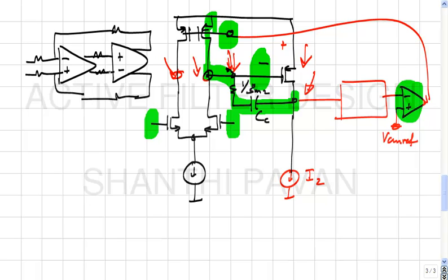So what he is saying is that okay, what about the input here, right. If I yank this now, will this guy get out of trouble, right. Please note that if this is 0, unless this is 1.8 volts, this will not go to 0.9, you understand. So unless you really wiggle, it will not get out, okay. So this is a very practical problem, and chips have failed because of this, right.